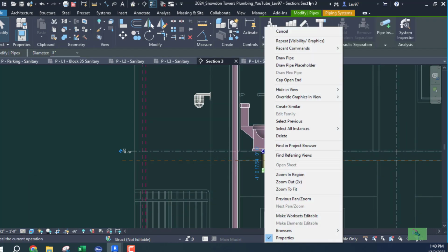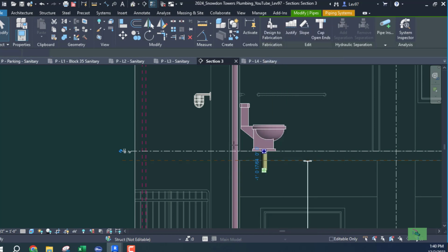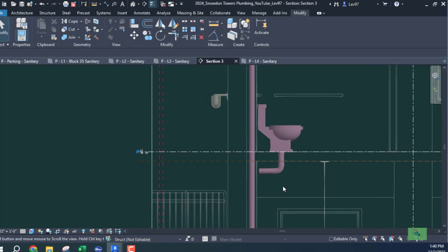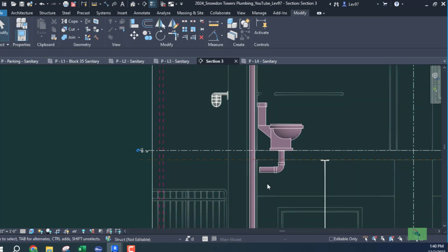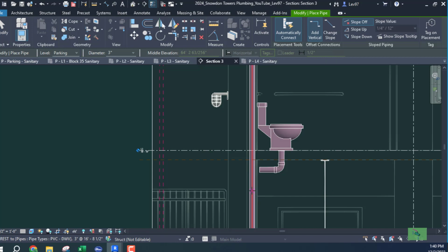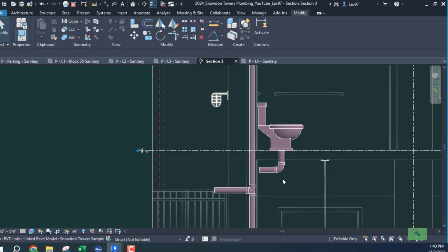So you come here, and you have to make sure that it's in line. And the way you do that, a lot of times you're going to be using construction lines. A construction line meaning you want to have your pipes lined up next to each other. And I'm bringing this on this side because I don't want it to overlap when I look at the plan view, okay?